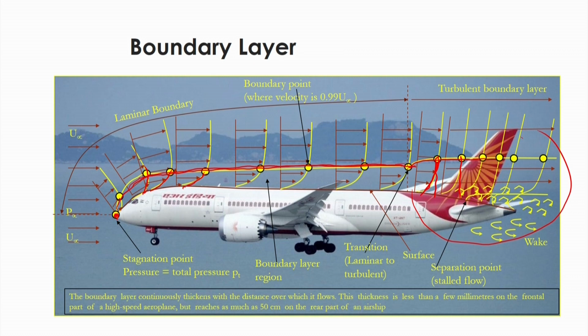The laminar sub region is sometimes called the viscous sub region, or viscous sub layer, and within that layer there will be more frictional force acting on the surface, whereas above that viscous layer you will observe relatively less friction, but still there will be a viscous effect, and it will cross the distance of the laminar boundary layer based on its turbulent condition.